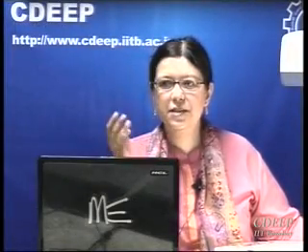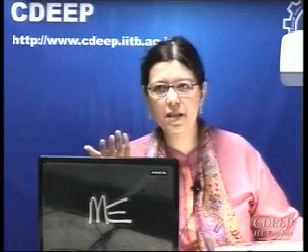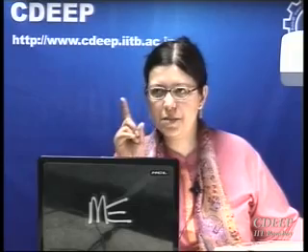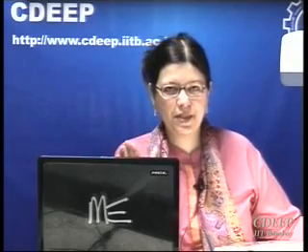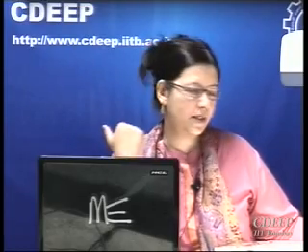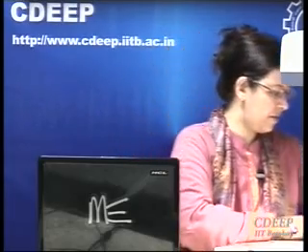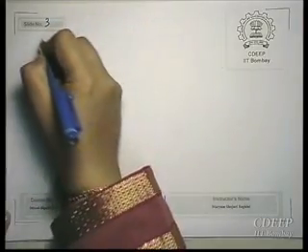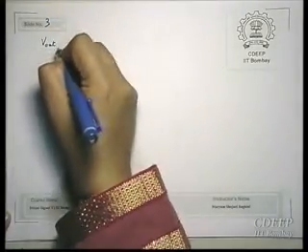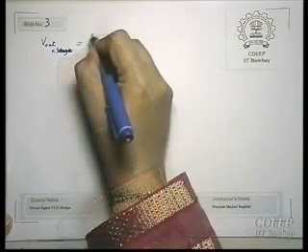Okay, now if you remember, we had this track and hold with offset compensation and multiplication by 2, everything and sampling in one stage. Do you remember? It was a switch capacitor based amplifier, but it was just simply an amplifier. But this is 1.5 bit per stage. Therefore, you need to have 3 cases, right? And this is differential. That is why I just explained how it works. So eventually at the output of every 1.5 bit,